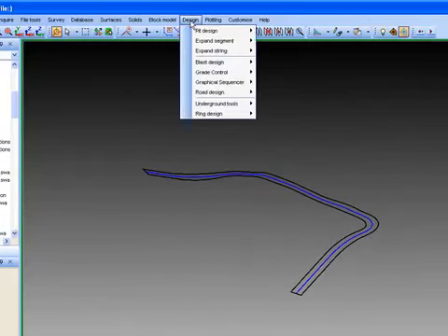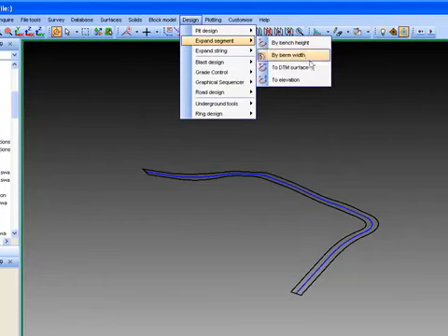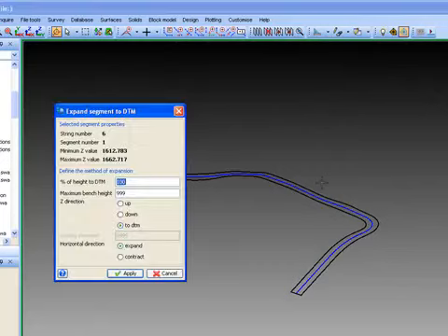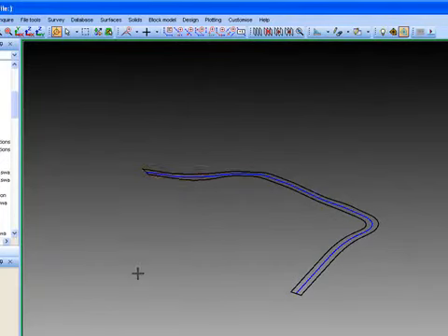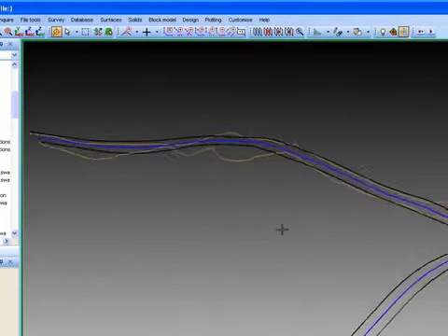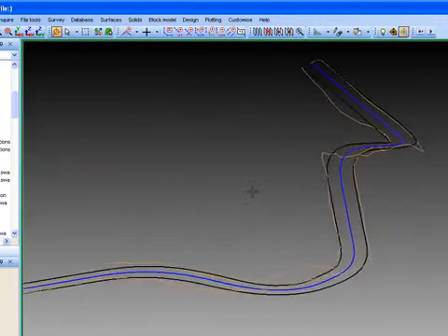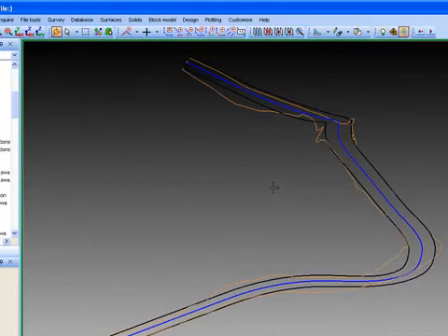This road outline can be projected up and down to the surface topography. Different angles for cut and fill can be used. And now we have essentially the intersection of the road with the surface.